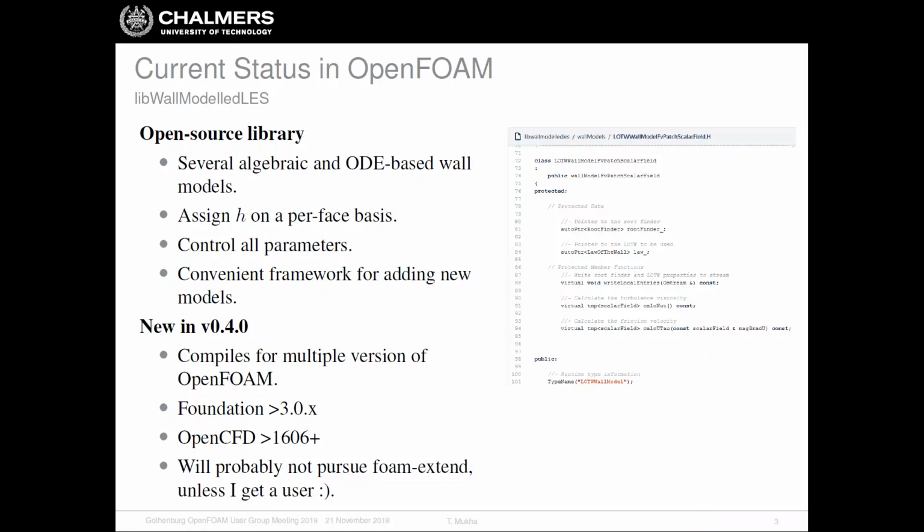So what we have been doing in the last 3-4 years is creating our own library for wall-modelled LES in OpenFOAM. This is an open source library, so all of you can use it. It contains a couple of algebraic and also ODE based wall models, so much more than what's in OpenFOAM itself.